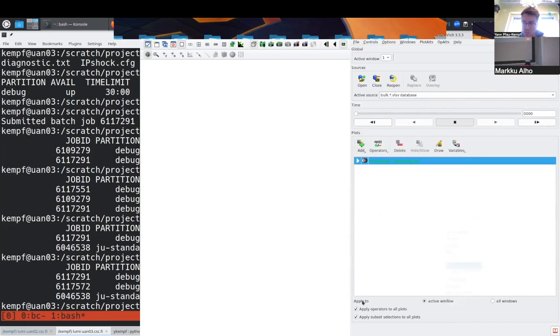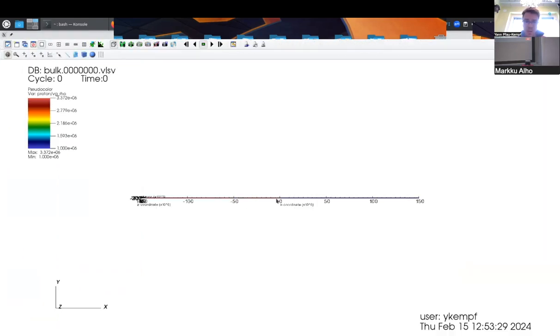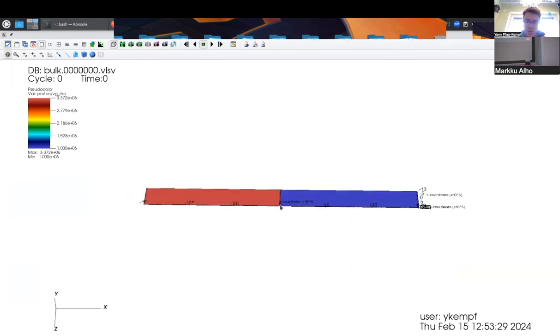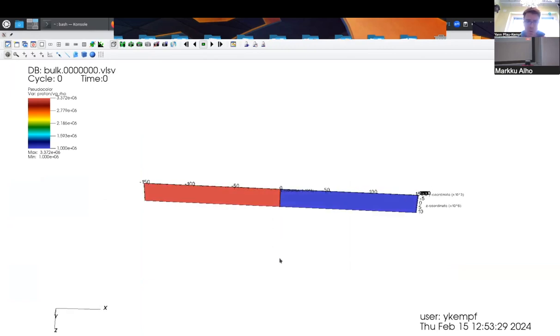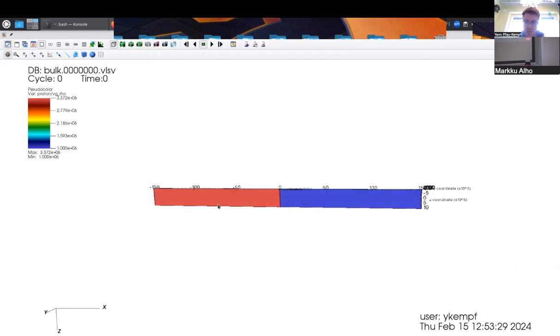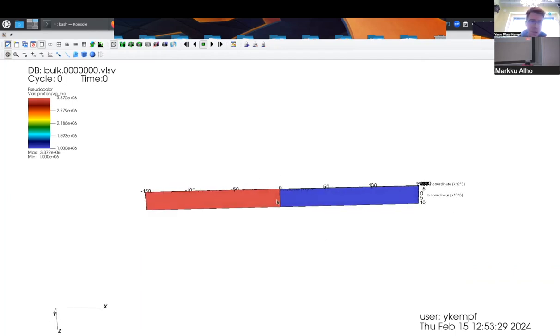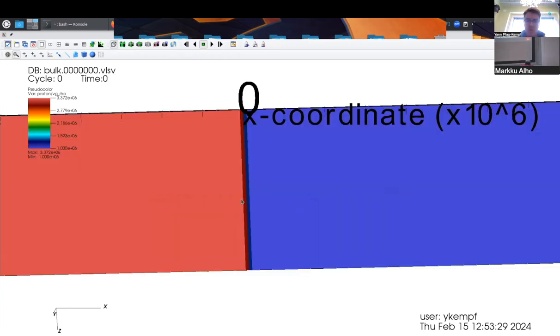So let's plot the density of our simulation. Let's just do the full plot like this and see how it looks. As we parameterized, we have a rather long box with a few cells in the transverse direction. This is a full 3D object, so it's a bit clumsy to plot, but you see right away that we have a high density region and a low density region. I'll zoom in to show you that there is a smooth transition there, but we don't have a lot of cells across that transition. It's apparently only about 4 cells from one side of the shock to the other.